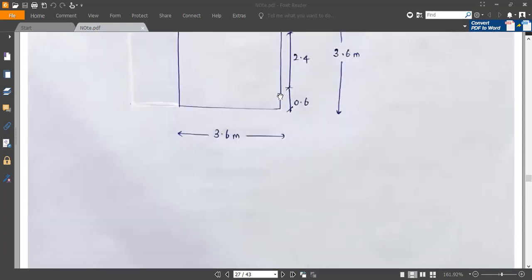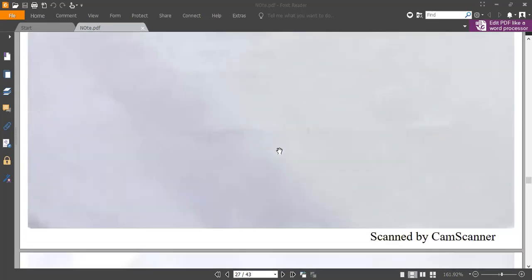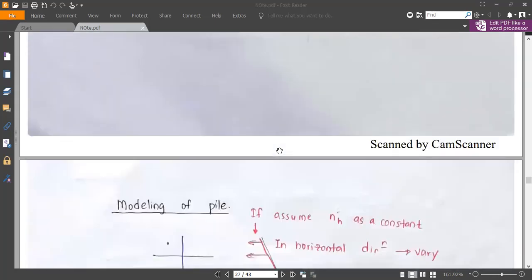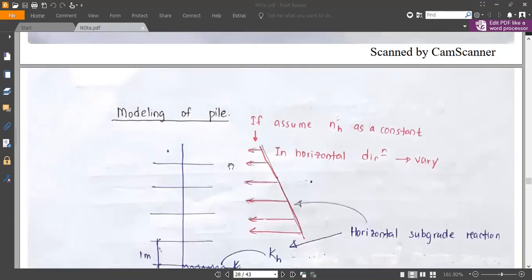And from the center of the piles towards the outside, you will have the radius and some additional spacing to bend the reinforcement. A minimum of 150 millimeters is required, so our pile radius is 500 and plus 150. So from the center to the end of the pile cap, we will have 650 millimeters, because we are bending and fabricating the reinforcement in the pile cap, as you may have seen, right?